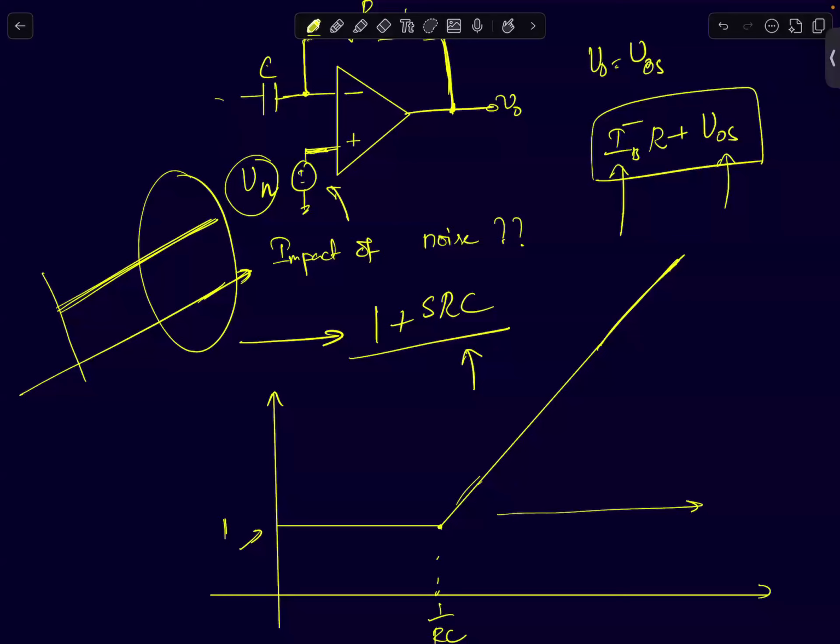And even your input signal can contain some noise. Input is not just a clean input; it can also have additive noise. So this is Vi, and there can be additive noise at the input itself. What I'm modeling at the positive terminal of the op-amp is the op-amp's noise, the circuits present in the op-amp adding some noise. The noise I'm talking about here is from external sources.